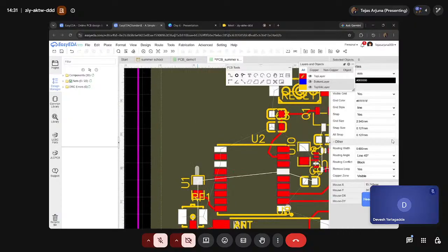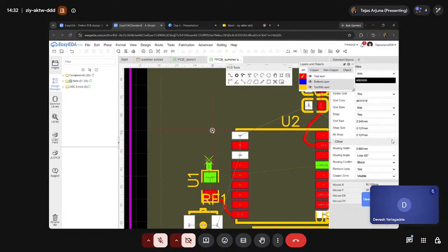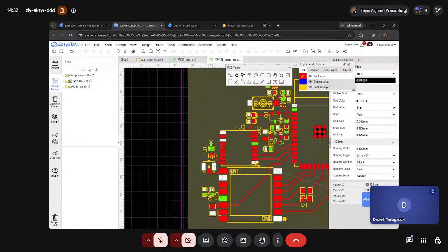Make sure that happens, because there will be a high amount of heat generation as more current is possible. So how do we do this? See, this is how we will connect the wires. We can directly place a wire here, but to show that we can, we are placing a wire and not using a through hole. I'm placing it over here. Similarly, connect everything.